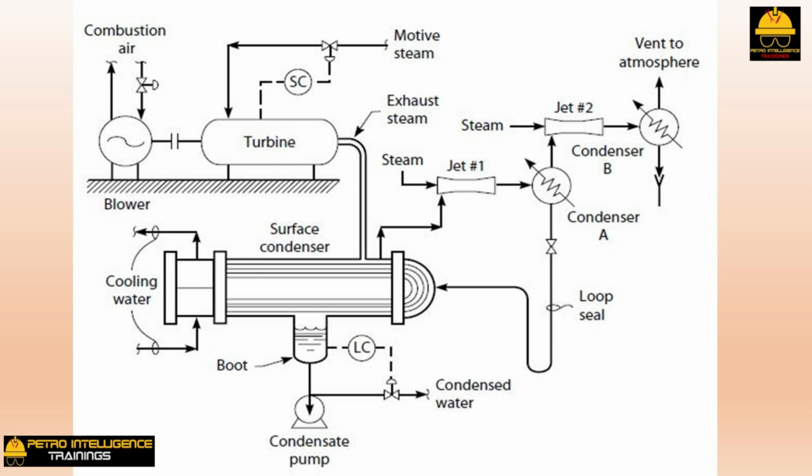What, then, is the true function of the final condenser? Well, if the tiny amount of condensed steam is not needed, the final condenser serves no function at all. It may safely be discarded. Why, then, do surface condensers come with final condensers? It is just a convention that, for most plants, makes no particular sense. It is really just a holdover from the design to conserve freshwater on the old British naval steamships.